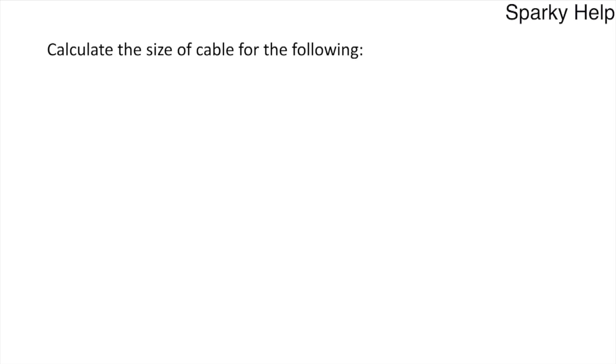As always with all these things, the best thing you can do is have a go. So let's just work through an example with you. Calculate the size of the cable for the following. We need information in order to work this out. Obviously, if it's your job you're working on, you would know, you'd check, make sure you're correct in what you're doing. So we need to know the load. Here's the load, 8.4 kilowatts.